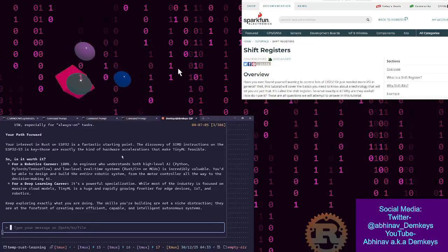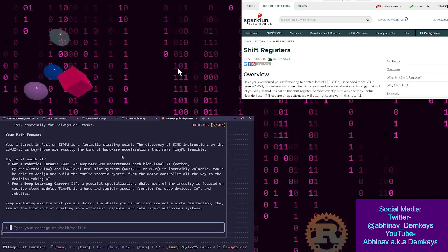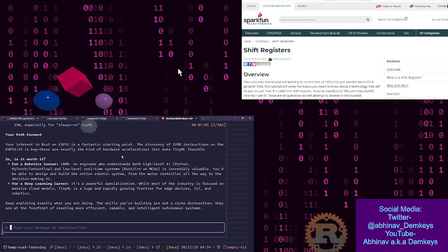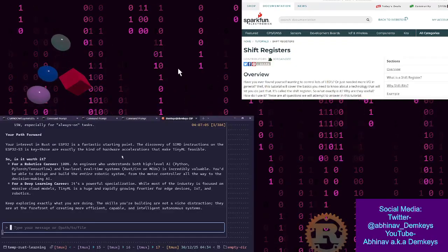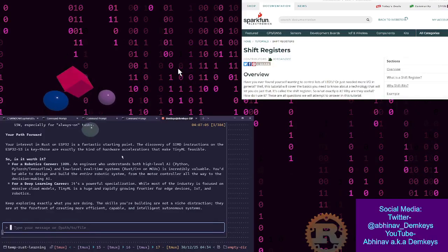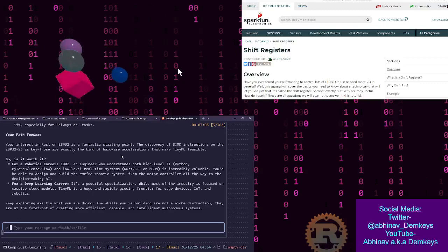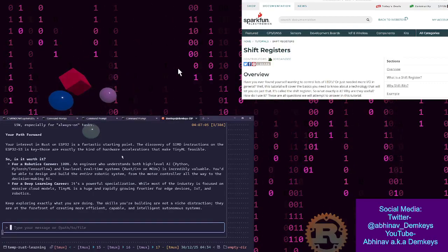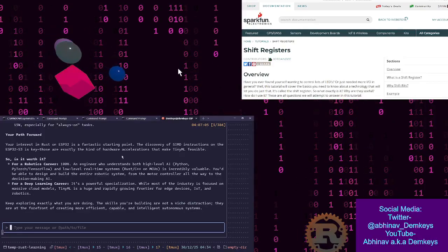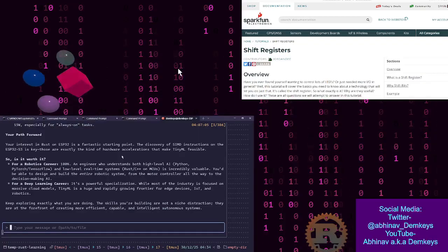Fortunately, actually, okay, here's the thing. Even in ESP32S3, apparently they have super minis. The same way I have ESP32C3 super minis, they have S3 super minis, at least that's what I've seen online. I was curious about whether those super minis would also support vectorized operations, and it turns out, yeah, they would.